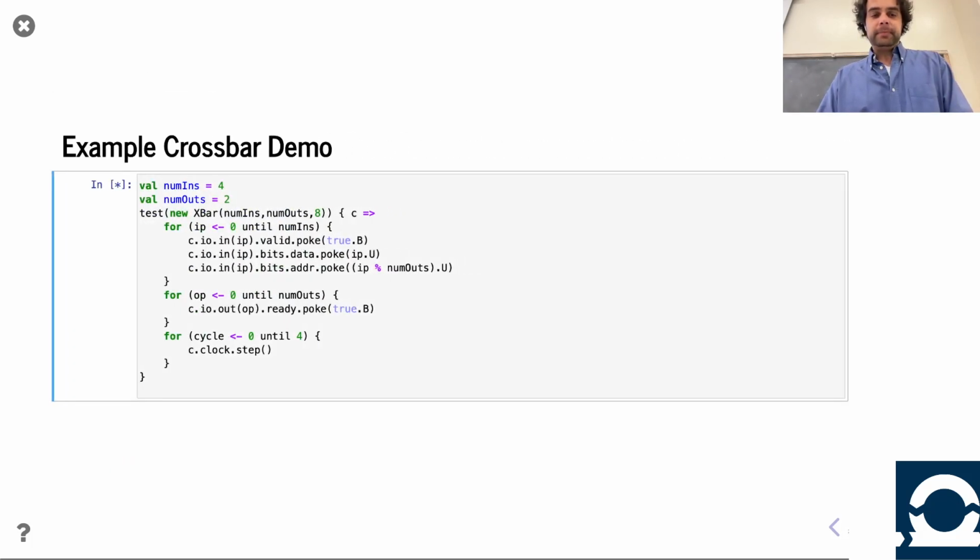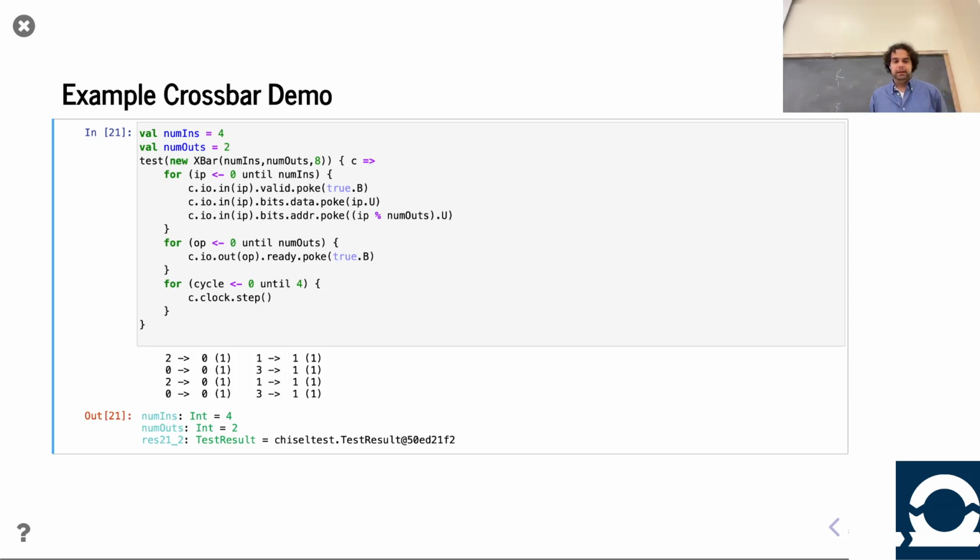If we go ahead and run this, here's this notation of which port is receiving. So this is port 0, port 1. This is showing the valid bits, and we make this test bench easy to read. The payload we're sending is what port is sending it. So we see, for example, the output port 0 is rotating between input ports 0 and 2.